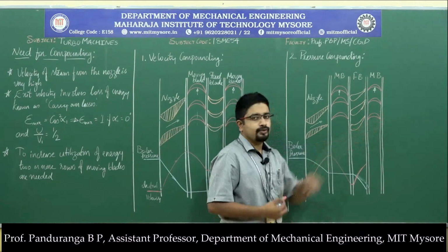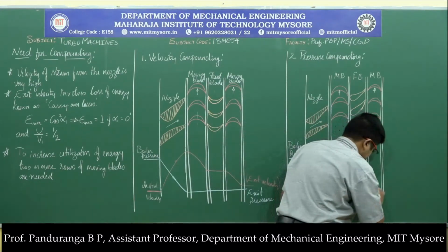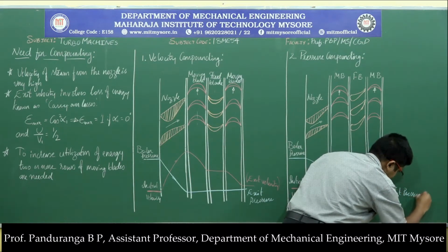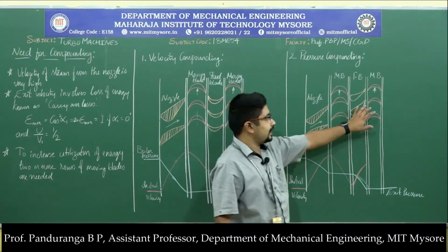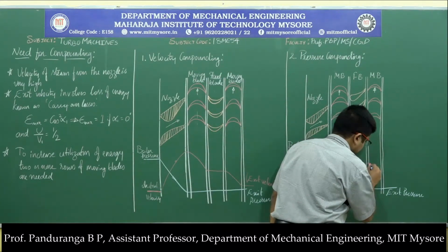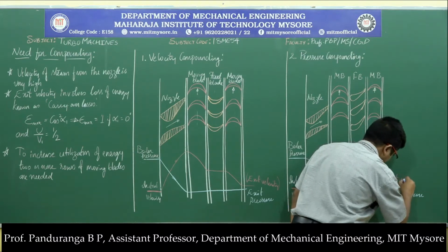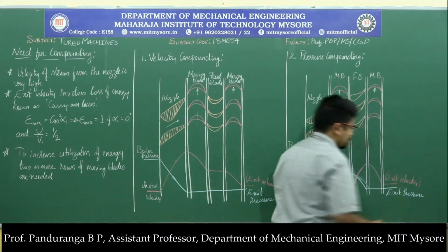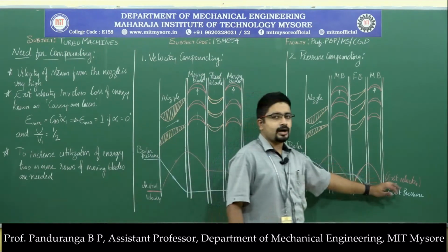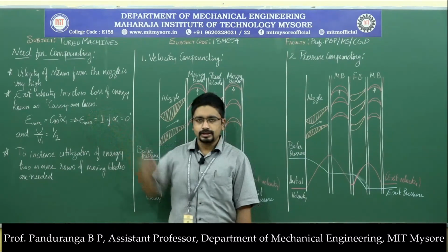Now the steam enters the moving blade. So here we have a symmetric blade, so there is no change in pressure, the pressure remains constant, and the steam comes out with exit pressure. Now as the steam passes over the moving blade, it absorbs kinetic energy, and the velocity of the steam reduces and comes out with exit velocity. So exit velocity squared by 2 will give us the carryover losses. Here also we can see that the steam is coming out of the turbine with a low velocity, which means to say that we have reduced the carryover losses.